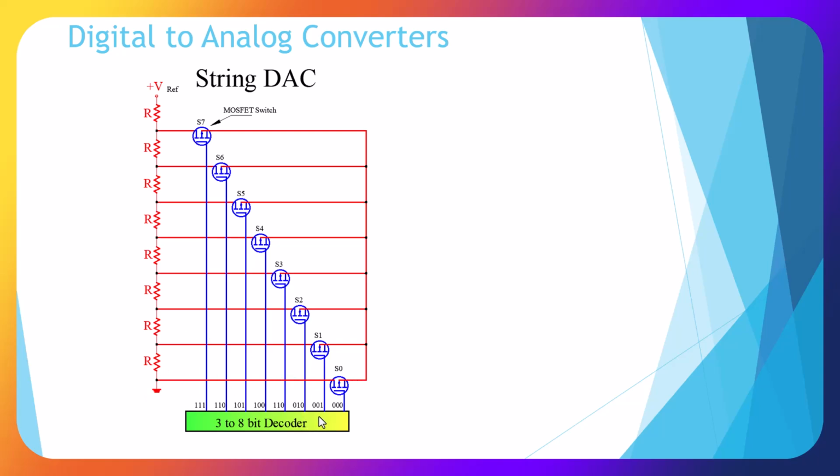And each one of these, if I fire this one it would be 2, and would put out this analog voltage at the output. And if I just turn this one on, it'd be the analog voltage of 7. If all of these are on, we'd get close to 256 being the 8-bit number. A similar unit would use currents on this side so that you would have a DAC that was putting out currents.